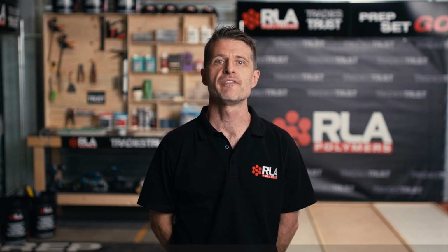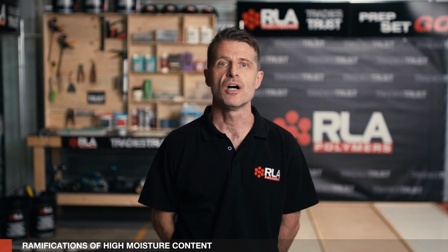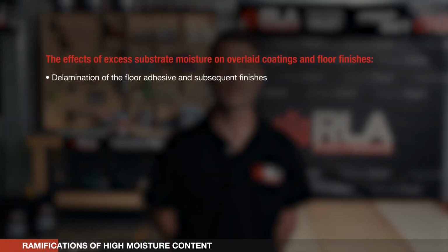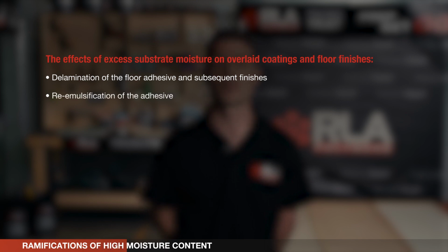So what are the possible effects of excess substrate moisture on an overlaid coating or floor finish? Now, it could be delamination of the floor adhesive and then finish. It could be re-emulsification of the adhesive, and this is when the adhesive goes back into a liquid state.